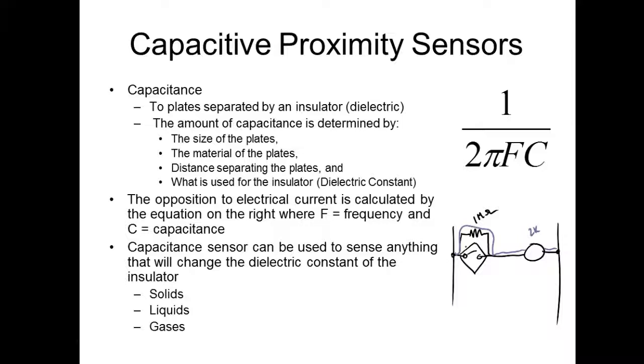So we can get these capacitive sensors that are electronic and they don't have to be powered. They power up through the circuit, right? You'll understand that. If it's a solid state sensor that needs power, then it's going to have a lead coming out the top or the bottom that goes to power. But these capacitive sensors and these inductive sensors are going to be two wires.